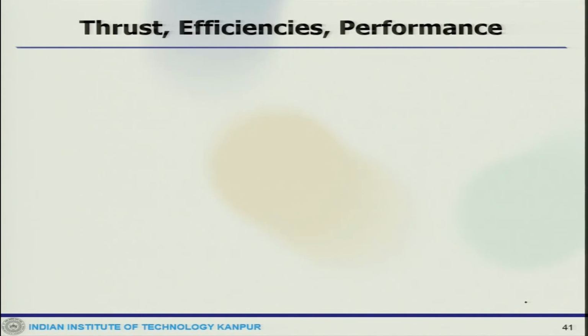Now we find out aircraft endurance. For a given fuel, the maximum endurance or time is obtained for the flight condition corresponding to the minimum rate of energy or power required. So we can find the aerodynamic configuration which provides the minimum energy expenditure. To do that we come back to this.